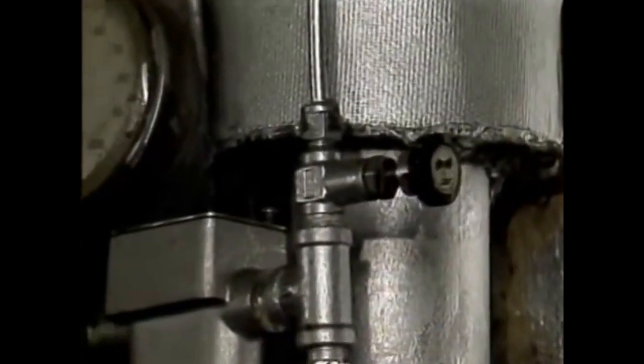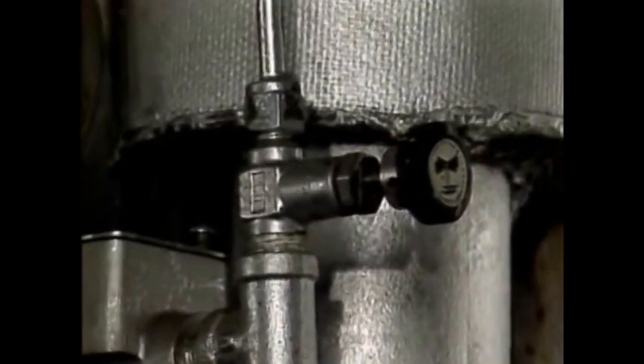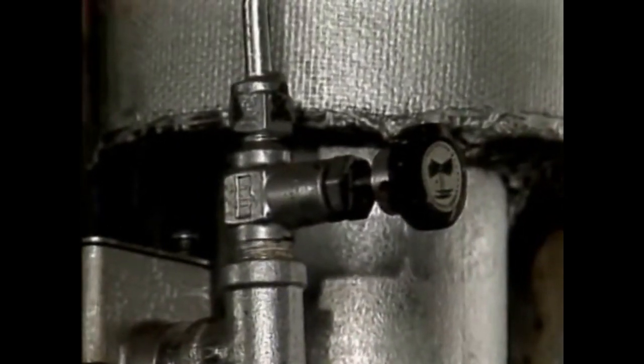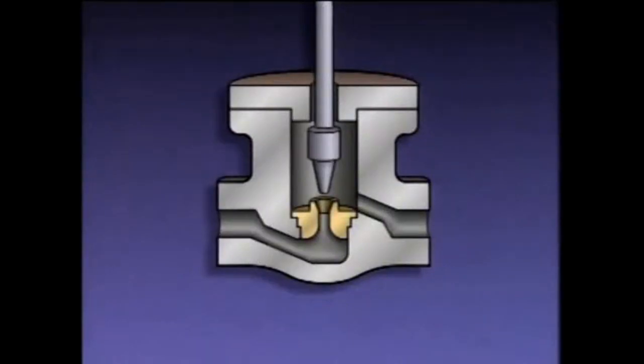Needle valves are usually smaller than other globe valves and are designed to give fine control of flow in small diameter piping. A needle valve has basically the same parts as other globe valves, but its disc is shaped differently, like a needle. The needle extends deep into the seating area of the valve. A small movement of the stem causes a small, gradual change in the flow rate through the valve. This gives the needle valve an extremely fine throttling ability.